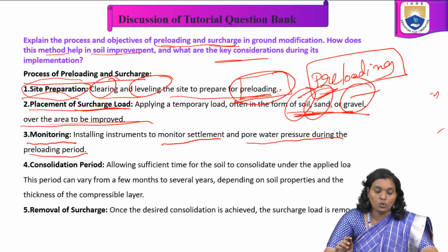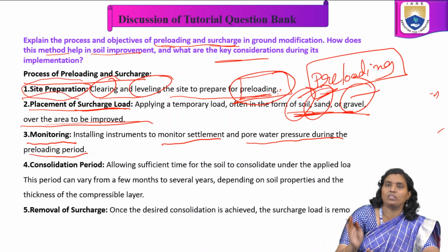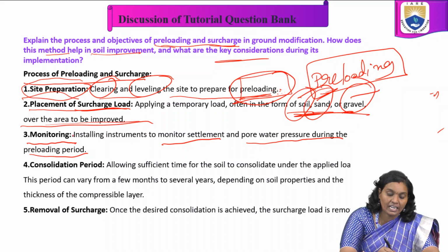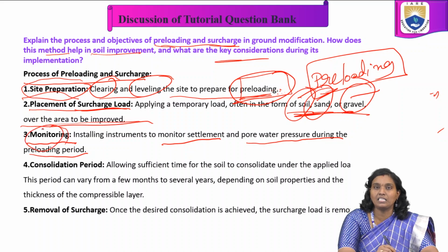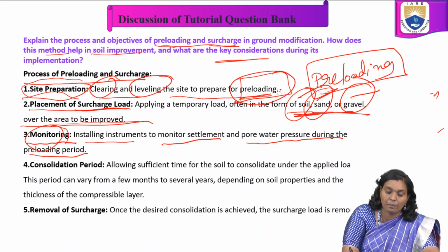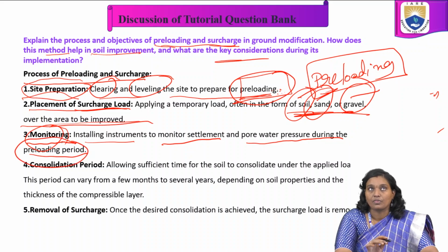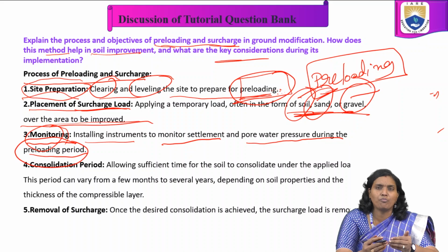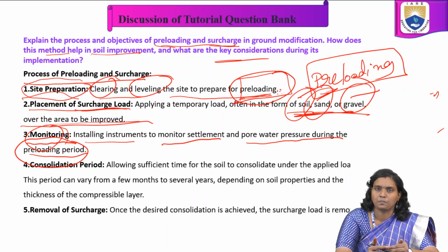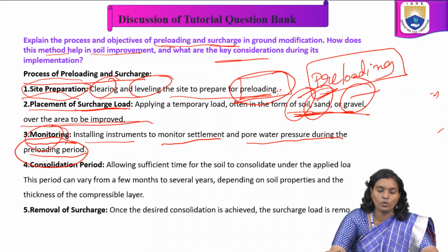We are doing this technique before the process starts, so the monitoring is important for preloading. We have to understand what kind of changes and modifications we are getting based on these temporary loads. As part of the preloading process, we have to monitor settlement and pore water pressure during this period.